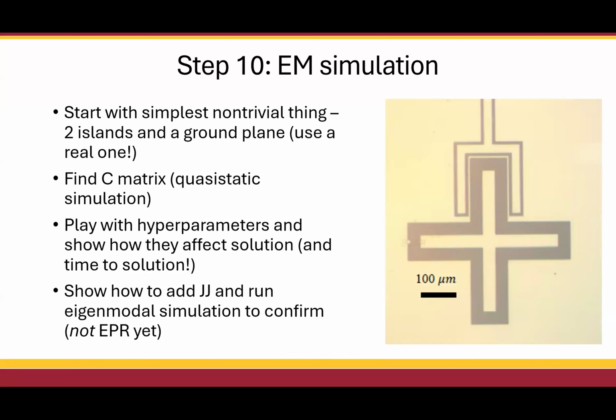All right, now electromagnetic simulation. Another thing that I had not implemented yet because Pallas was not good enough yet, but now it is. They did a new mesh refinement algorithm. Apparently it works way better now. So I don't have to get everybody an HFSS license. Now I can just have them run Pallas.